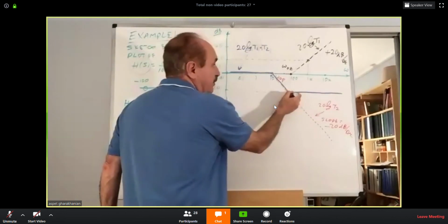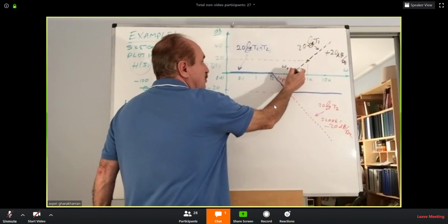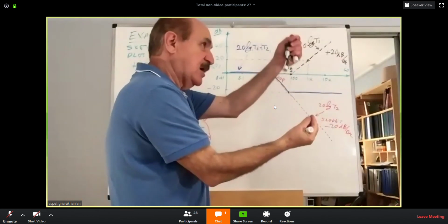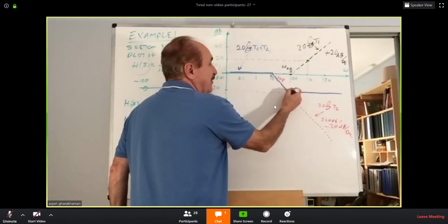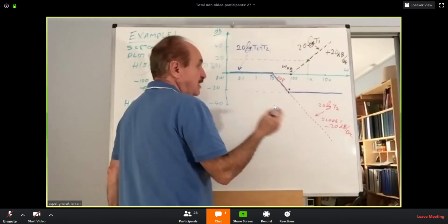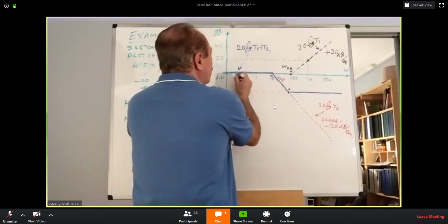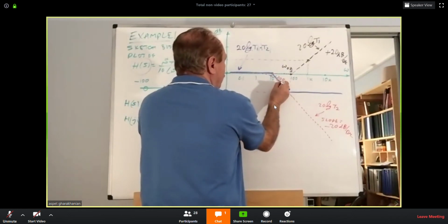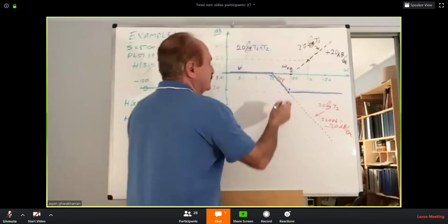In these corners, you should do a 3 dB adjustment to the top because for zeros, the adjustment was upwards. So it will be 3 dB higher than that one. Therefore, the refined curve has got to be something like this, going through here, then through there, then becoming asymptotic.